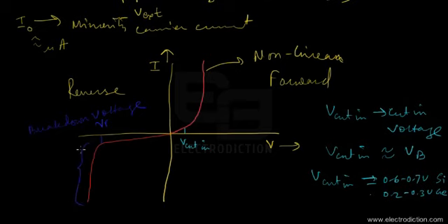So when the diode crosses the breakdown voltage, it enters the breakdown region, where the reverse current through the reverse biased P-N junction diode increases significantly, even with minute changes in the applied voltage. At that time, upon the conduction of severe amounts of reverse current, the diode junction breaks down in most cases, and the diode suffers a burnout.